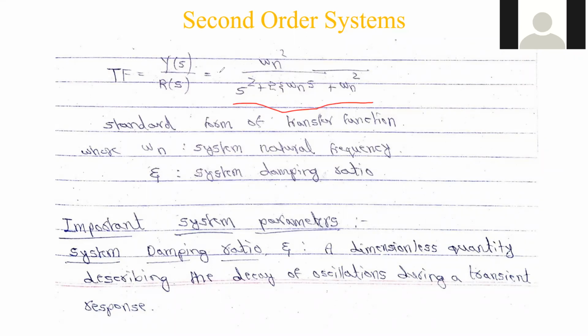What I need to find is y of t, the time response, that is the inverse Laplace transform of y of s. For that, what I have to do is take this r of s in the numerator, and then substitute for r of s the step input's Laplace transform. Okay, that is 1 by s. So when you substitute that, you have to do this simplification to bring it into a form so that you can apply the inverse Laplace transform. Okay, so that is the derivation, the steps. So we try to do that.